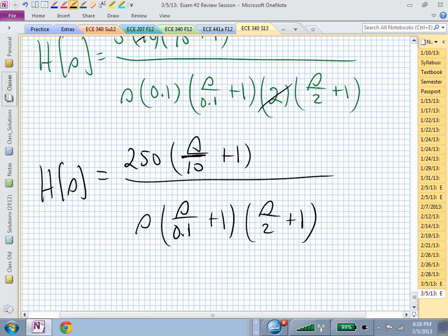And that's what I want you to be comfortable thinking about. Even though this pole at the origin is sloping for low frequencies, at 0.1, before we hit omega equal to 1, it's going to get a kink, and it's going to start sloping even more than it was. Then what do we come to next? Well, we come to this next pole.